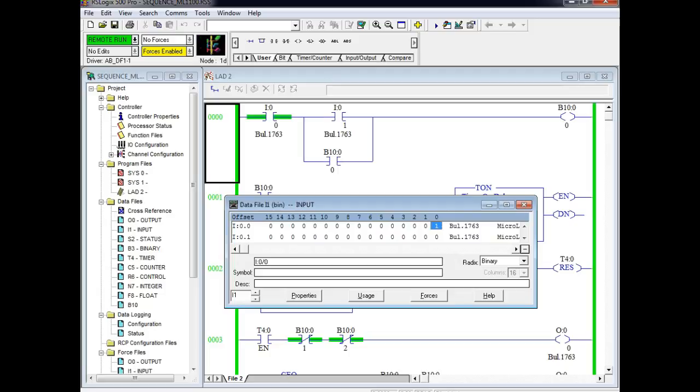It means my push buttons are hooked up for sourcing, and my inputs are hooked up for sinking. Y'all understand that? It means I take power and hook them up to my switches. So I'll use plus 24 volts for the common on my switches, and every time I press a button, it's going to put a voltage into this input.